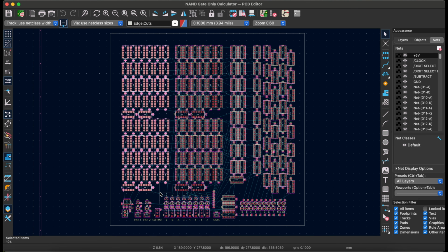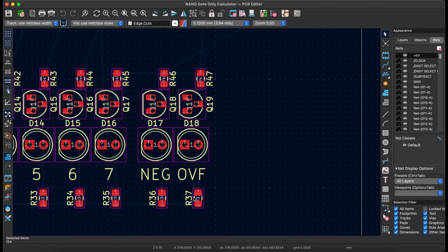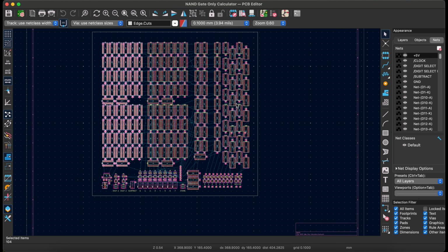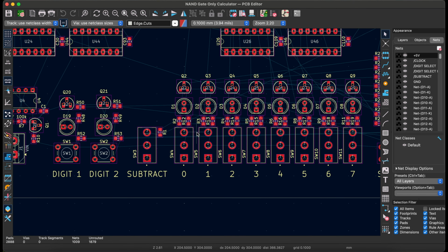That's also the range on the output. So if you do 127 plus 127, it will overflow. So it's not a very advanced computer, but it will actually tell you that it overflowed, which is really awesome. And yeah, it's just a small 8-bit computer that can handle signed numbers. I think it can also do unsigned, actually. You just have to read the binary differently. I'm not 100% sure. Negative numbers in binary is something that I still need to learn more about.